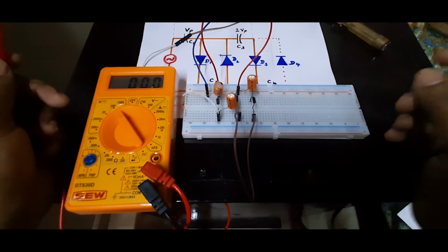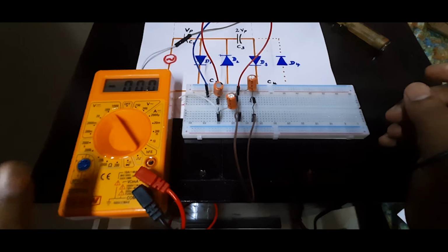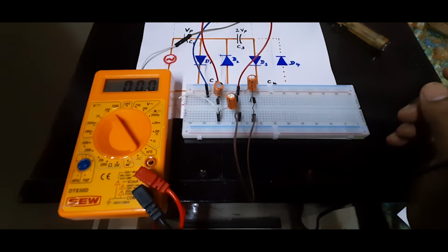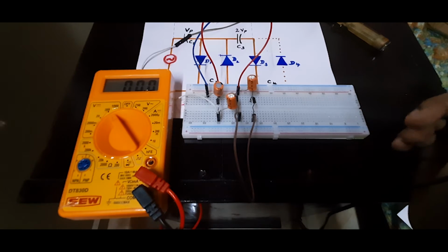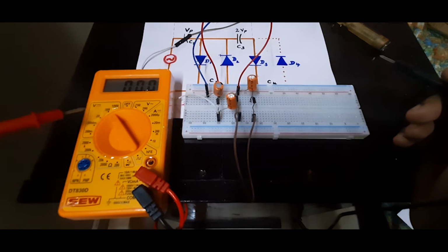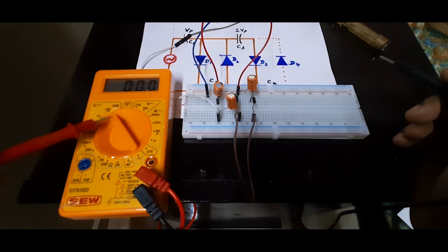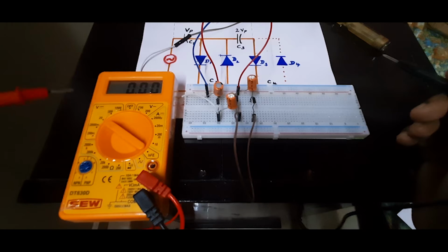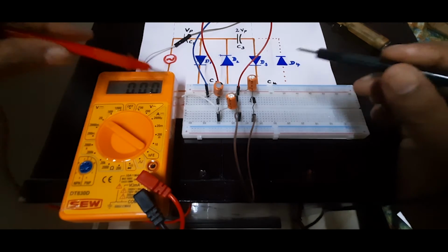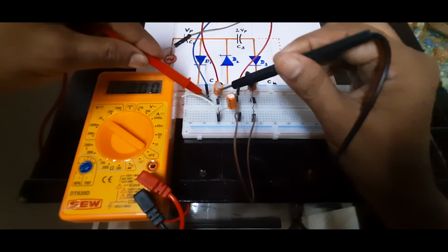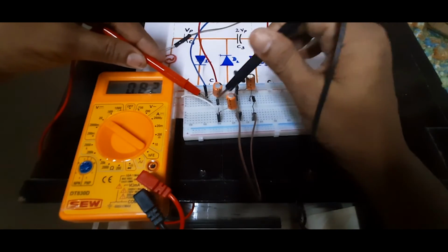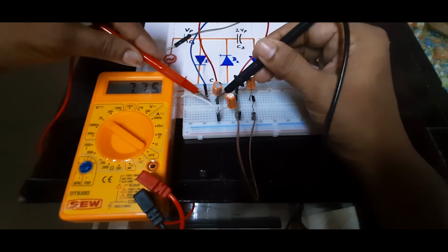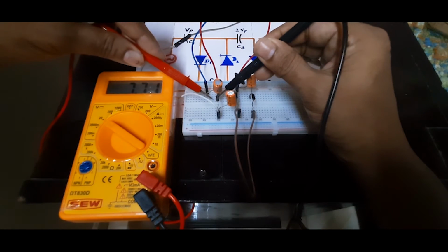Now, actually we should also measure the AC input voltage, that is the RMS value of the AC input voltage. These I am measuring as DC voltage. Please see the knob here. I can put it in 20 if this is the DC voltage. I put it in the 20 range. So once again we can do a more accurate measurement if it is in the 20 range. So please note down if there is any correction.